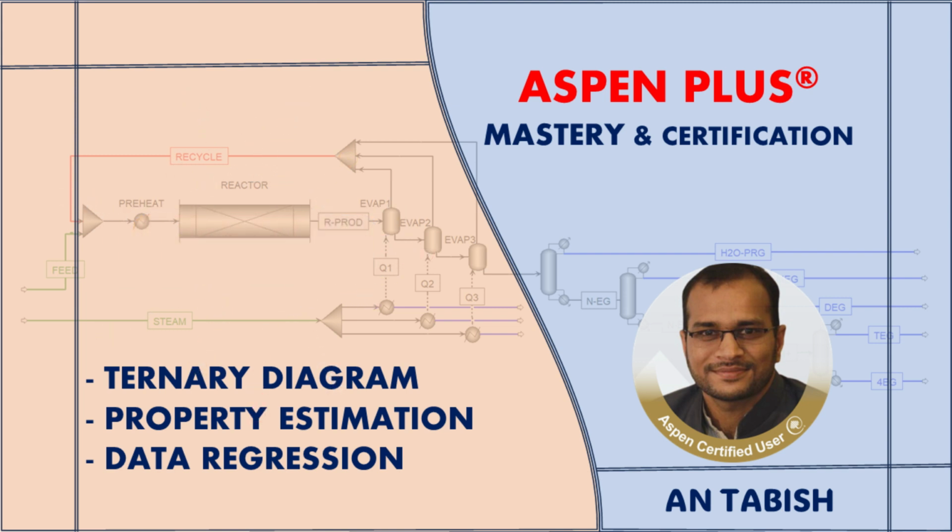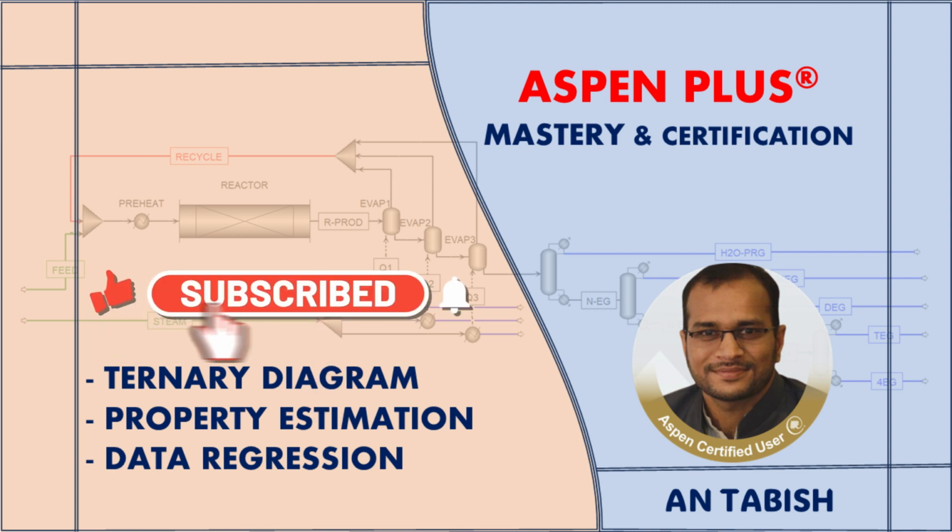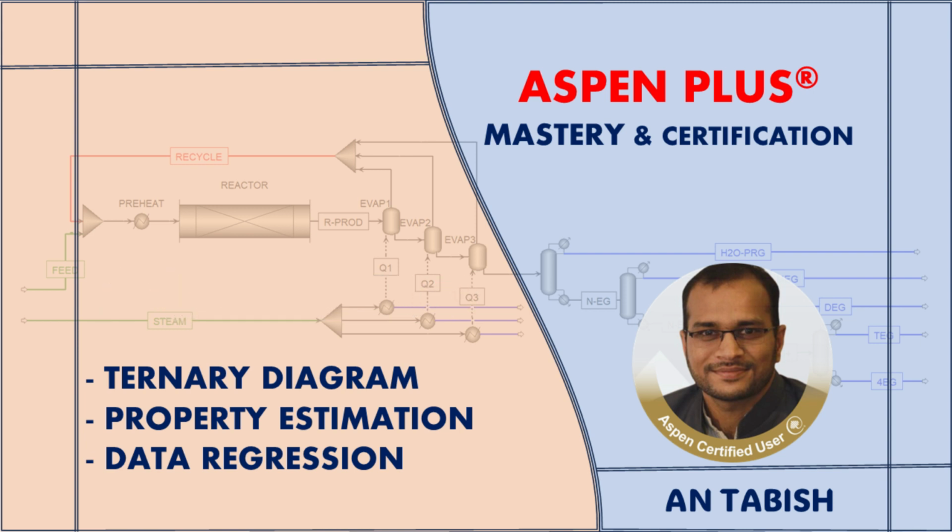My name is Tavish. In the last video, we had a comprehensive discussion about property analysis of pure components and binary systems, and specifically emphasized the thermodynamic property analysis of these systems. In this video, we will learn how to perform property analysis of ternary mixtures, specifically mixtures that form azeotropes, learn how to perform property estimation of non-databank components, and how to perform data regression to determine the parameter values from the experimental data.